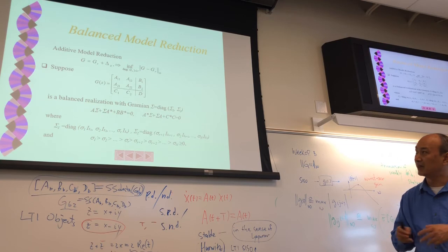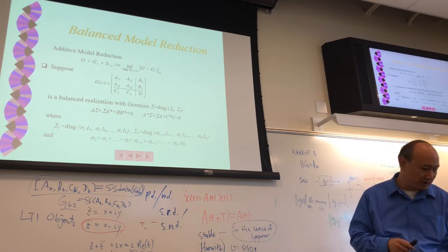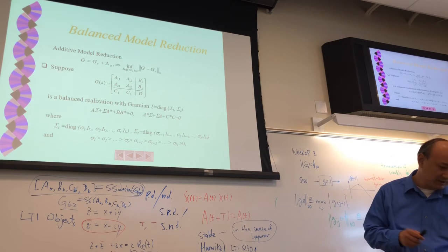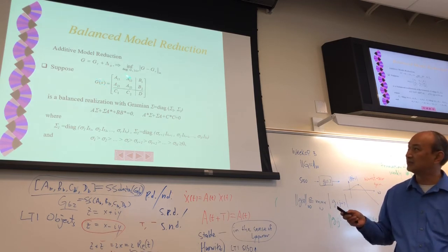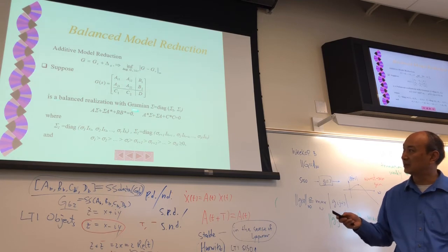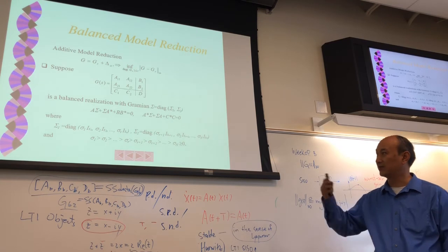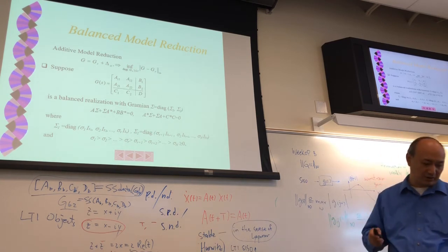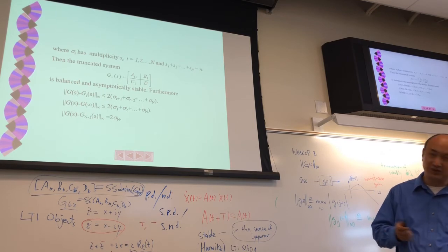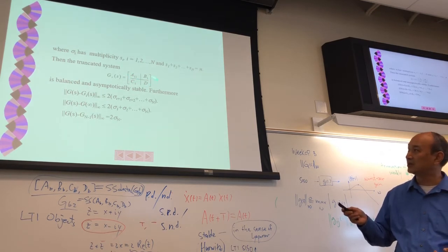So then what's the model reduction, and what's the beautiful side here? After reduction, G is the original one. So you have the original system like this. Then this one has a balanced realization like this. Then in this case, you have sigma 1, sigma 2. So this is sigma 1 to sigma r, sigma r plus 1 to n. So then you rank this thing we have seen before. So then we are going to do a truncation. The G r has A11, this was left.